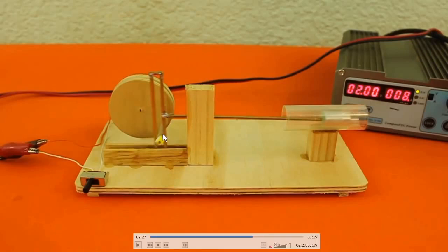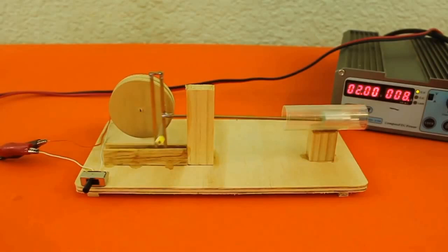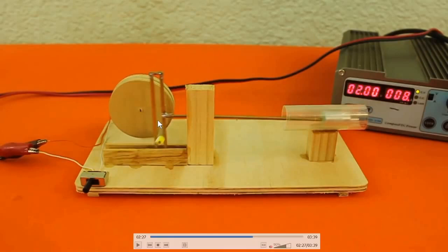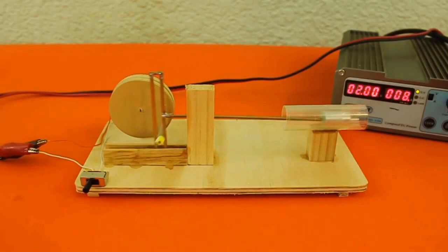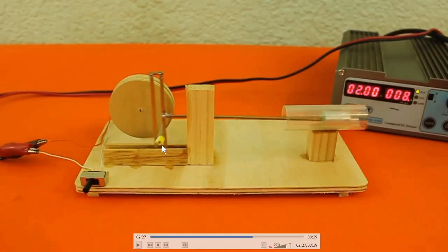Instead of connecting the end to the crank directly, they are providing a slot there. So when the slot is provided, what actually happened is that the turning pair between crank and connecting rod changed to a sliding pair. That means one turning pair reduced and one sliding pair introduced. Thereby it is a double slider crank chain inversion.